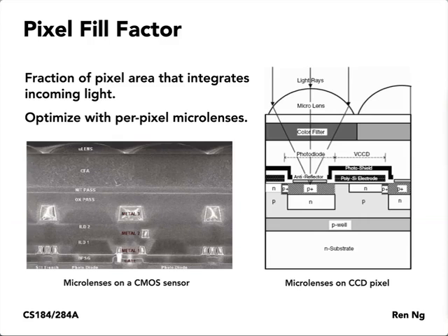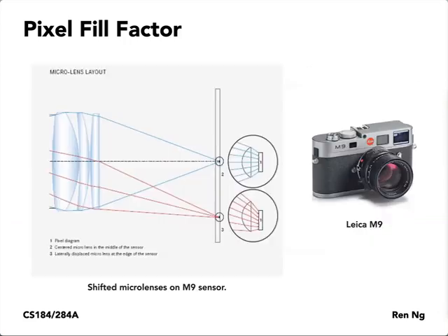Here's a picture of it. So here the rays come in, they get bent by a microlens to curve in towards the photosensitive portion and avoid the metal layers, okay? It turns out designing these has a lot of subtlety to it and is actually a pretty high precision task, and a lot of work has gone into optimizing this over years and years of sensor fabrication.